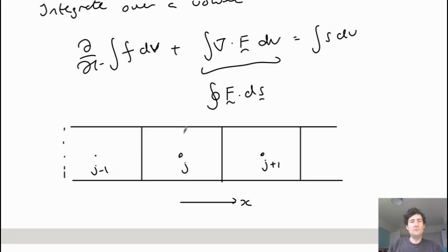And what we're going to do is to evolve or solve this equation. We basically solve either the average of f inside each cell, or the finite difference way is you solve f on each cell center. In one dimension with uniform grid spacing, it doesn't matter which you do, you end up with the same equation.